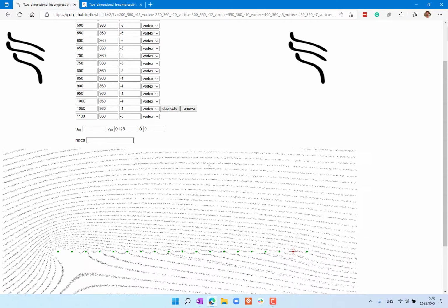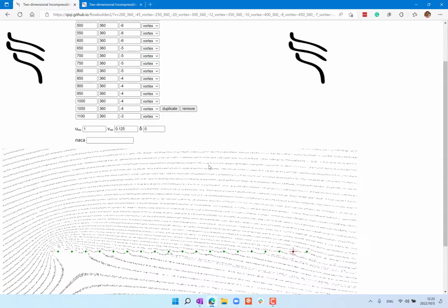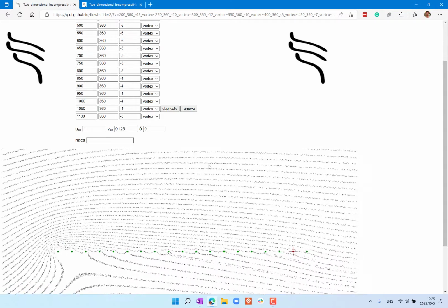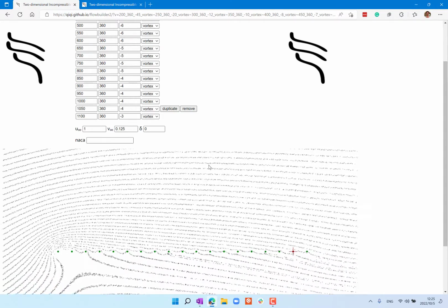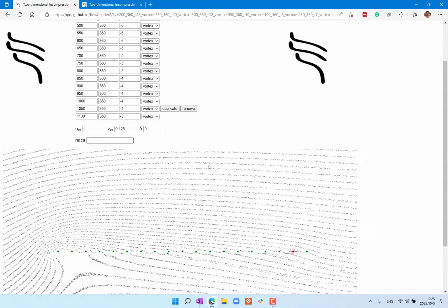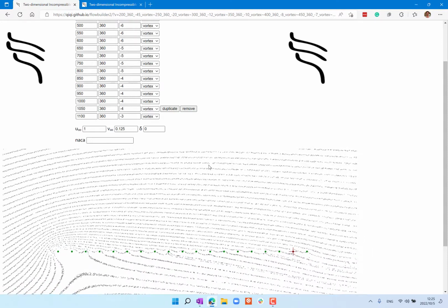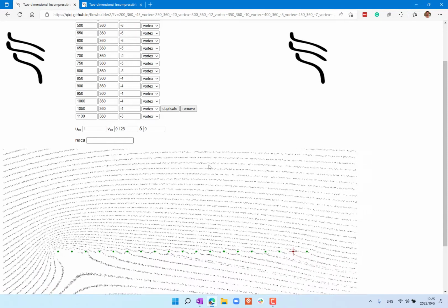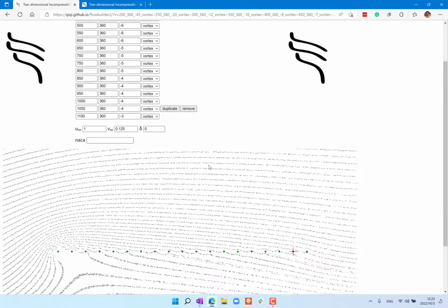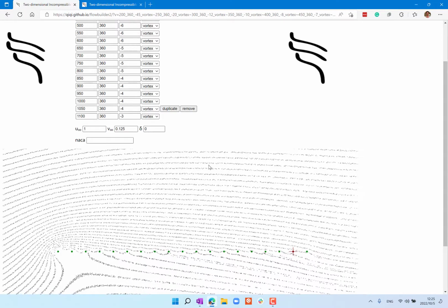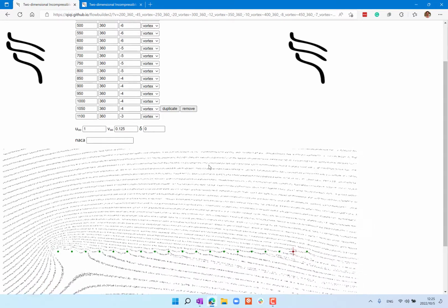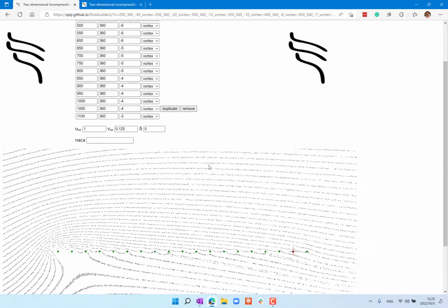But if you change the angle of attack by increasing V infinity, then you would actually get a uniform velocity. So if there is no V infinity, even for an arbitrary airfoil, you get an airfoil where the flow is tangential to the surface, and you increase V infinity, what happens? What happens is you add this V infinity to all the flow velocities everywhere, right?